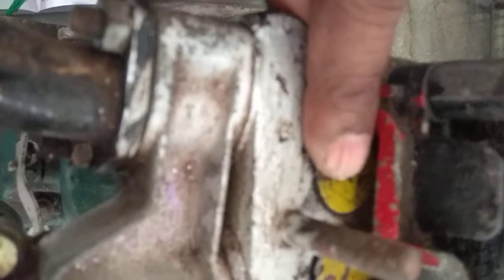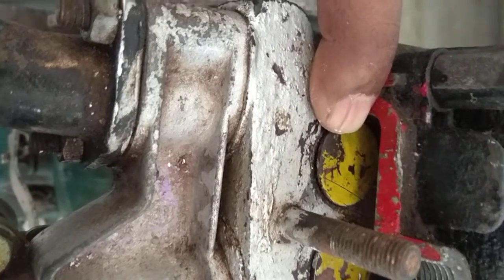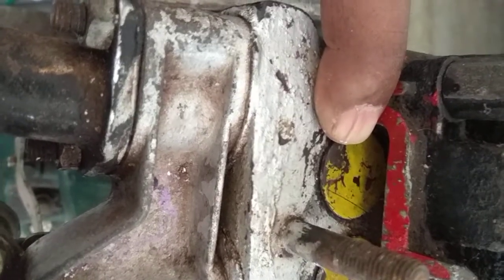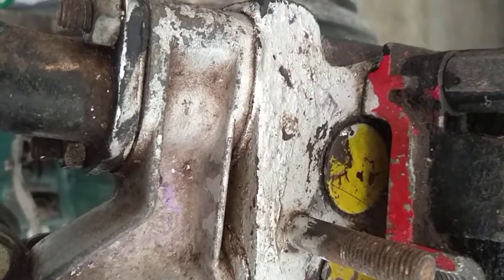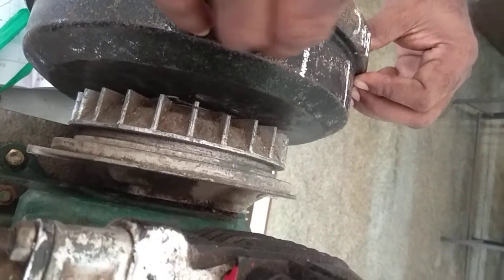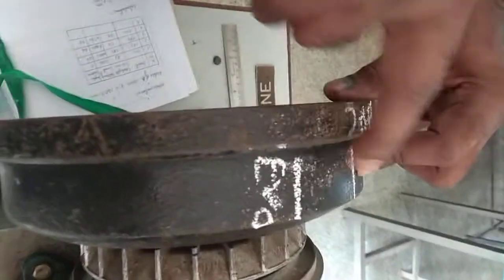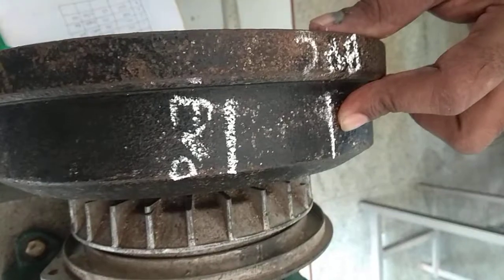Now this is the exhaust valve. We will note down the exhaust valve opening and closing values. So keep rotating the wheel. With respect to the reference line, the value is before BDC. EVO, exhaust valve opening, has just opened in this condition. Here EVO is before BDC.